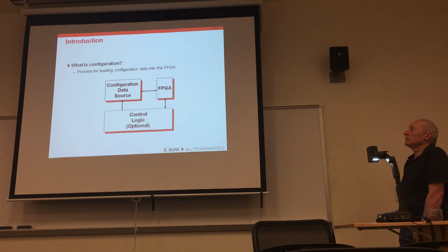In the end, every configuration scheme has advantages over another. Some configuration modes are designed for debugging, while others lend themselves to maximizing the system's available memory resources, and still others might give designers a choice of vendors. Choosing a configuration technique just requires the user to understand what their system is going to have and to anticipate what they're going to need their system to do. In some instances, customers build their configuration scheme to include multiple configuration modes, so they can test and debug their system through one configuration scheme, and then configure their FPGA through still another scheme after the product has been released.